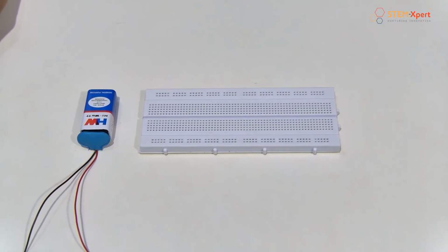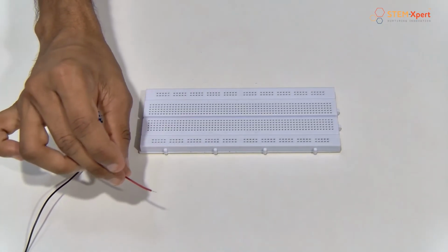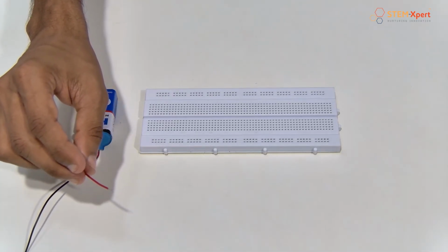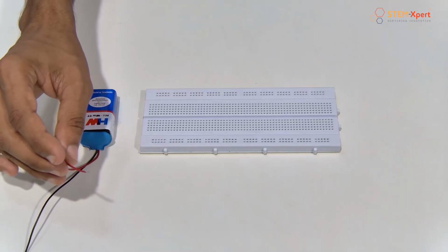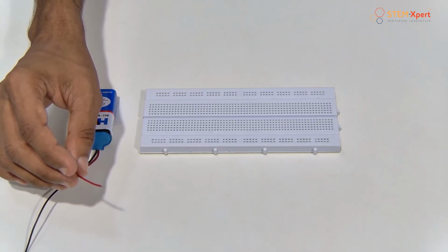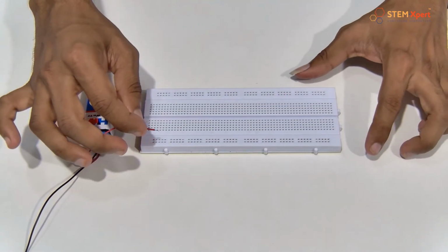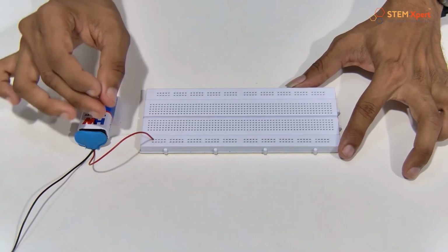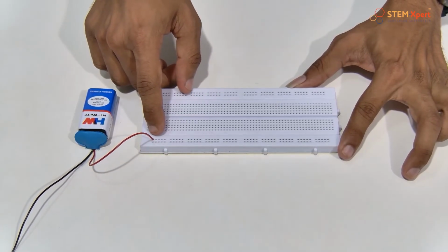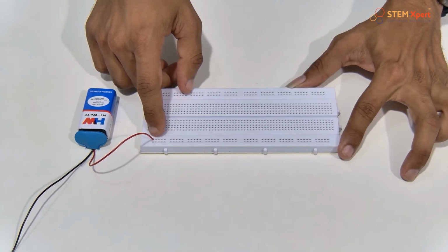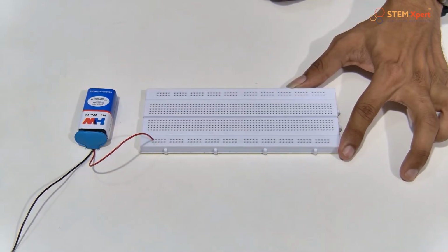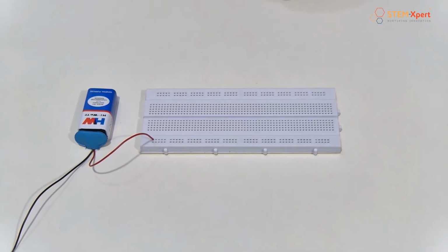Okay, now our next step is to connect the positive along the A part of our breadboard. We know that according to our circuit diagram, the connection starting from the positive of the battery, that positive is connected along to two different resistors. Am I right? So here I am going to connect the positive of my battery along with the A part section of the breadboard. Then also we know that when we connect a positive point along with the A part of the breadboard, then this entire point up to 5 section will act as positive.